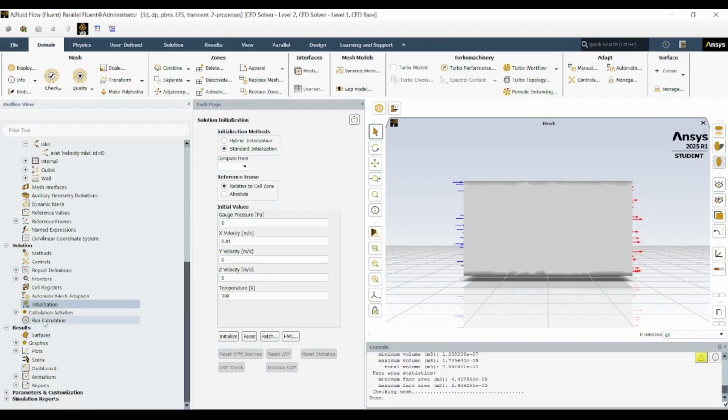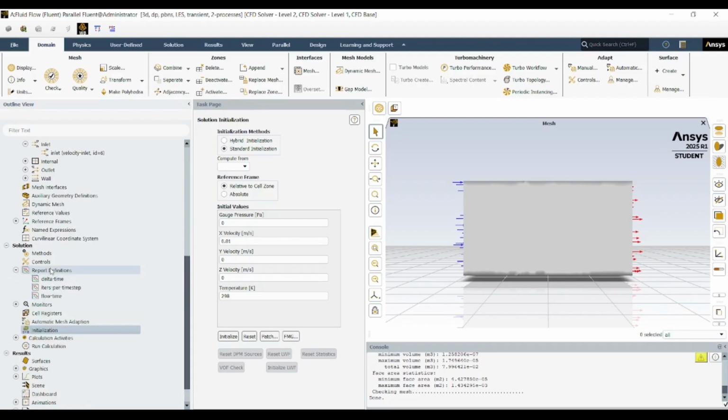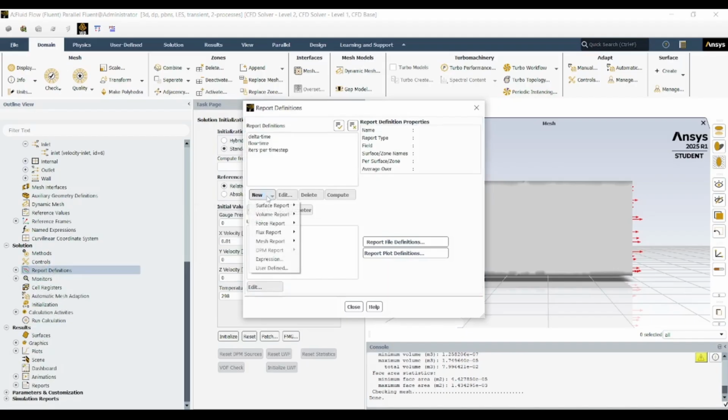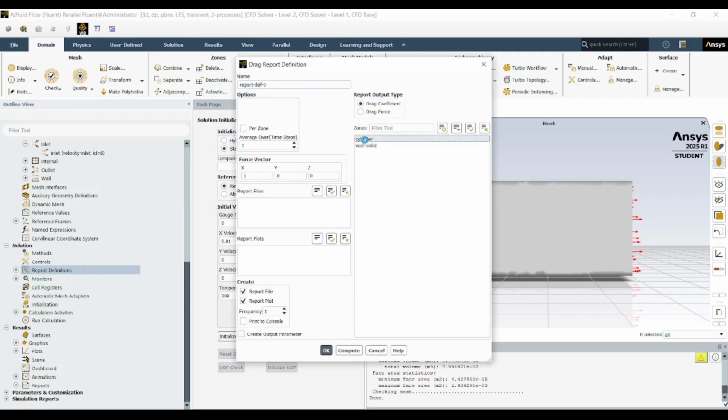In transient cases, you'll see vectors forming circular motion patterns behind the cylinder that change direction with time. This is direct evidence of vortex shedding. You can animate these vectors over time steps to visualize the alternating rotational motion.